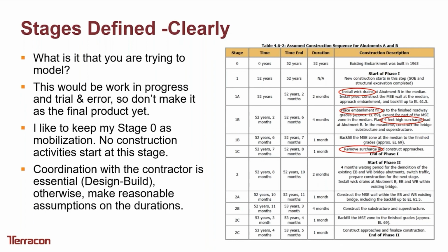And as I mentioned, for this particular project the existing bridge had to be operational, so we still have cars passing by, and we have limited time. We have to construct one side and then move on to the other, replace the bridge, and then complete the construction. So the very limited time is basically what made us go for the wick drains.